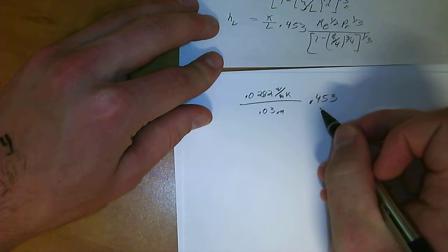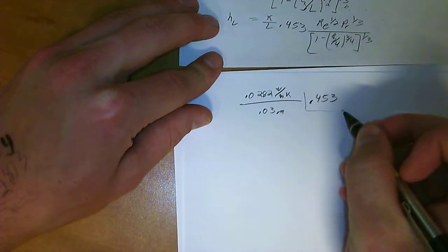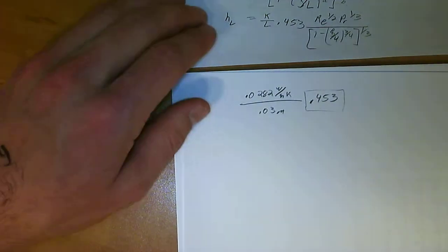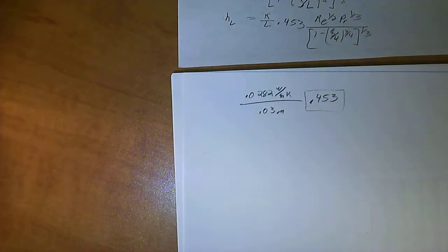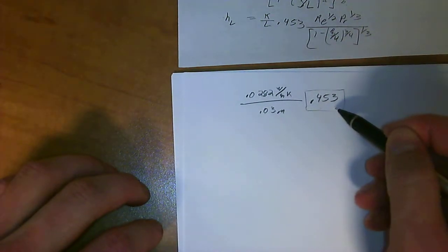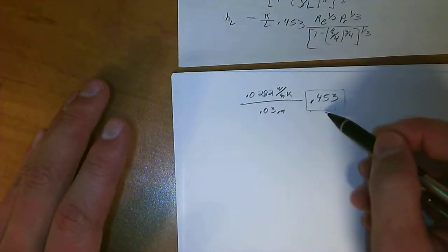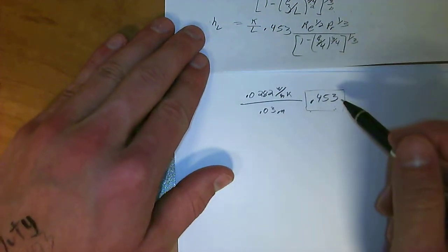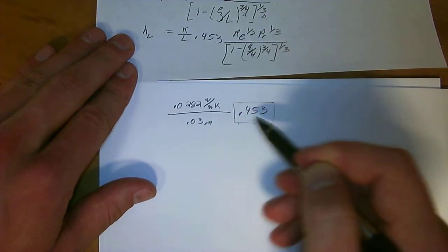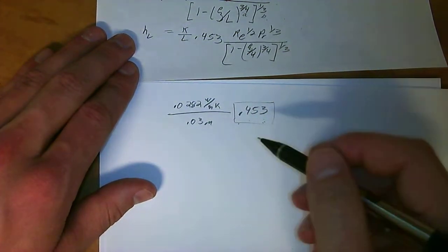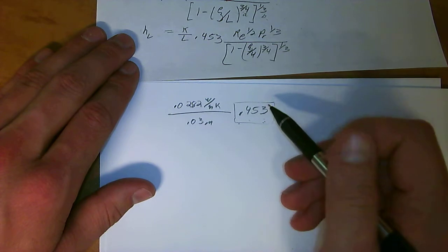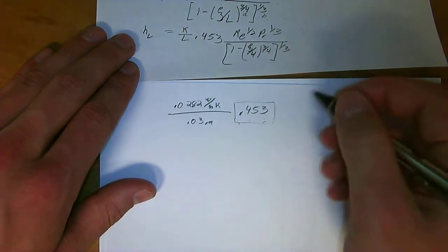0.453. I'd like to talk about this 0.453. This kind of varies from equation to equation. It's not an absolute constant. And it's weird because the Nusselt numbers vary like that, and I really don't have an explanation for it, except that, well, that's the way it is. So talk to your professor about the Nusselt equation that you want to use. Sometimes this coefficient is like 0.65. Sometimes it's 0.45. And I've never really had an explanation of how you decide what this value of the Nusselt number equation is. So just be wary of that and compare it to your own notes in your class to figure out what you're using for this equation.